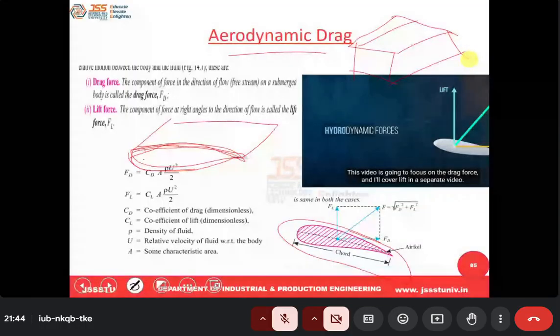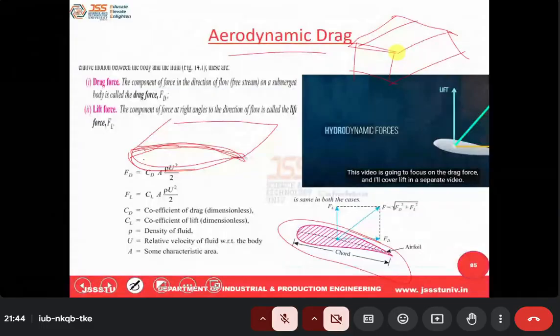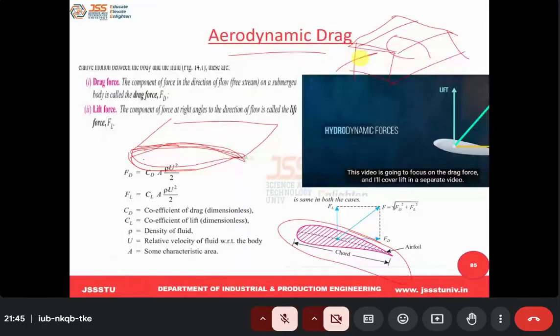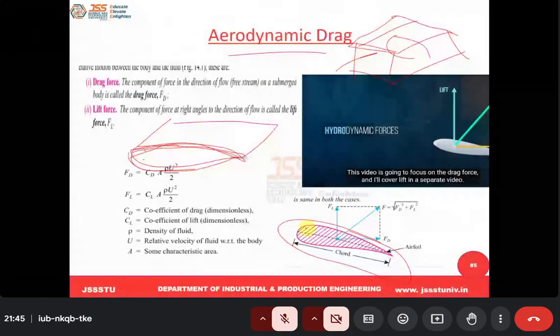In the wind box they made an experimental rig, made different types of airfoil profiles, and passed air over them to test which one would give the highest lift. Believe it or not, they tested more than 10,000 types of profiles with different cross sections, and finally they arrived at this shape, and this shape gives the highest lift action.